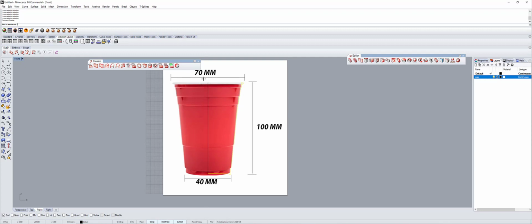So I'm going to click from the top to the end of the pattern and click it, and now it's doing the turn. So you have to have Full Circle enabled here. The full circle represents 360 degrees, okay? If you don't have Full Circle enabled, it won't do the 360 degrees. So now it already did it.